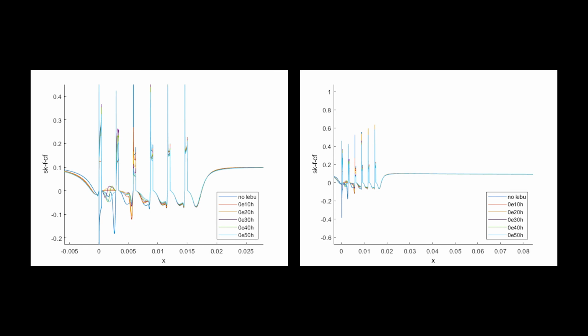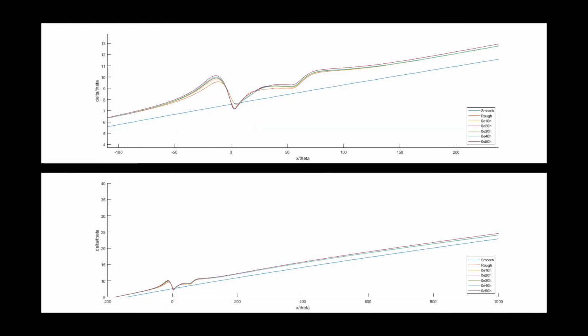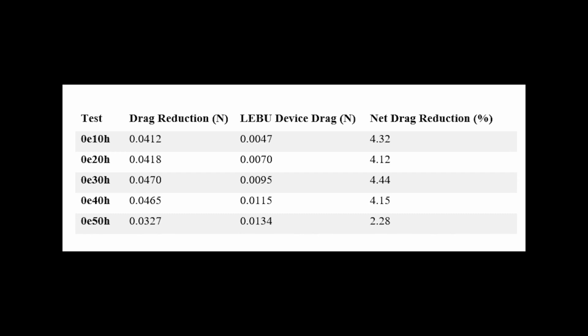The testing has mainly been looking at the skin friction over the wall when LEBU devices are placed in various positions above the rough section of wall. The boundary layers were also analysed to get an idea of what was happening after the rough wall and LEBU interaction. Actual testing was broken up into several cases, 1 through 5, each with one variable change to see its effect on plate drag. The final results of each of these cases were the reduction of drag and percentage net drag reduction.